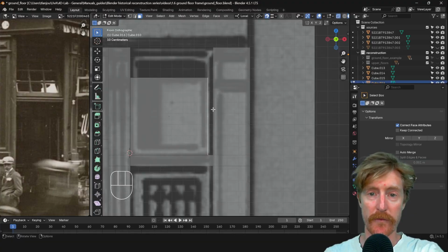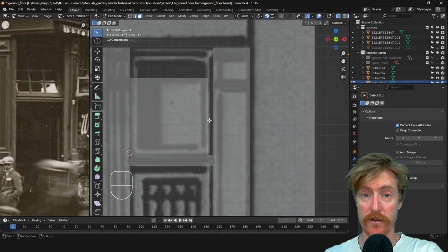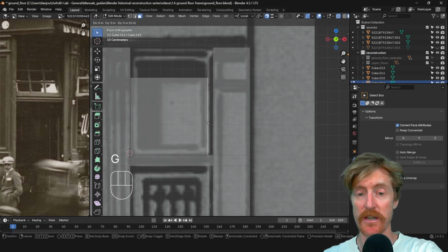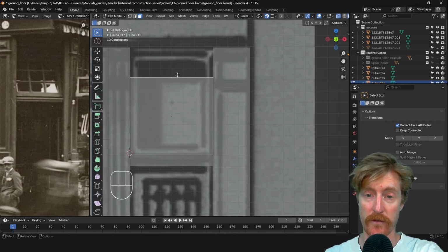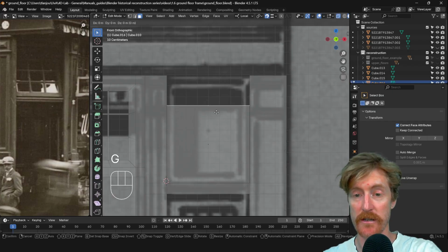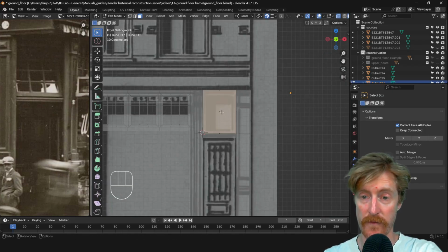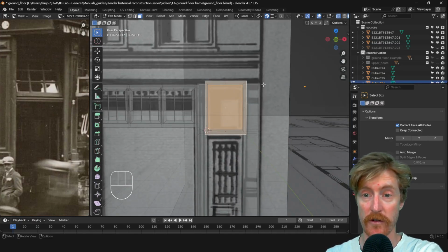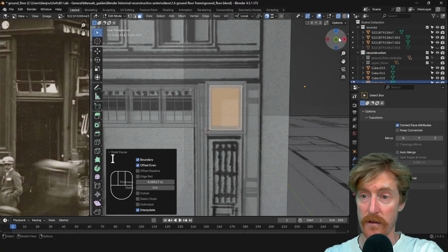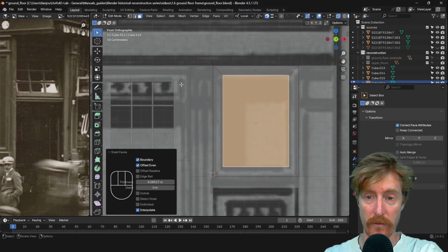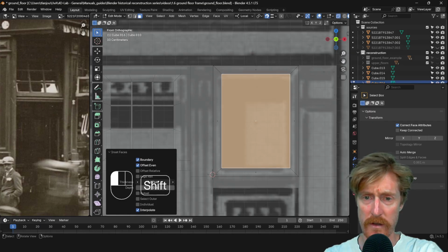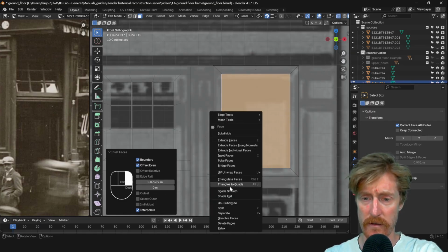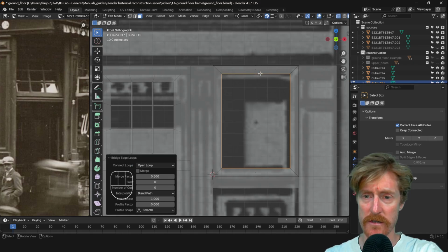And to model a little bit faster, I'm using now the keyboard shortcut for movement. So I'm not picking the move tool. I'm actually using G on the keyboard, and then you can see it starts moving, and then X to move it on the desired axis. G, Z over here. Select the front. And now I'm also using this keyboard shortcut for insetting. Go in front to make it a little bit similar to that one, and then select bridge faces.